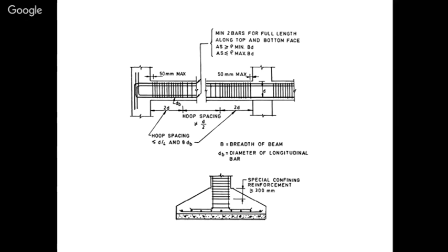This is how we have to detail the beam as well as the foundation point, because I have clearly shown you in the image that plastic hinges will not form in every column portion except at the foundation level, because plastic hinge formation occurs exactly below the column part, very close to the foundation. At that time our foundation should be able to resist a large amount of lateral force.